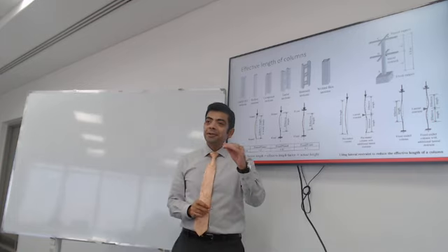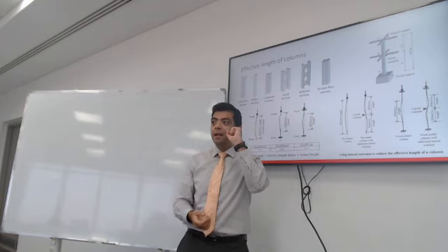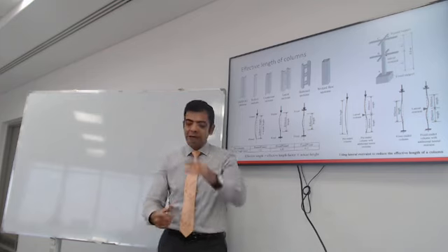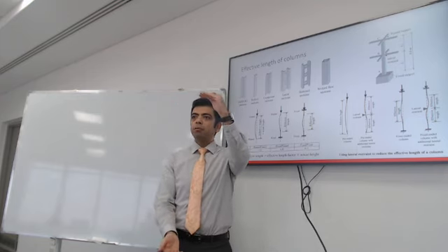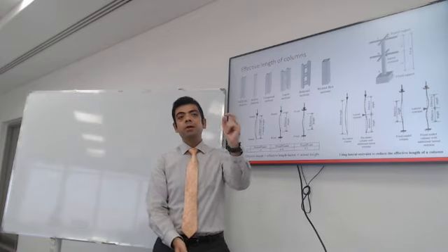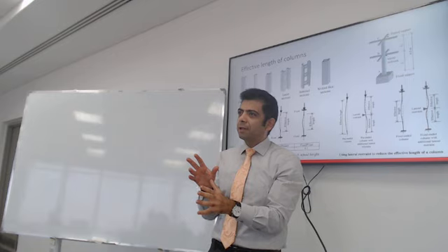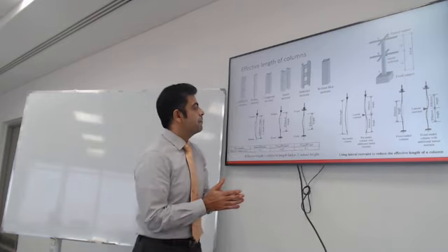The critical axial load that will result in buckling depends on only two things: the length of the column and the geometry of the cross section. So which length of the column do we use? We use something called the effective length, not its actual length. So what is the effective length?